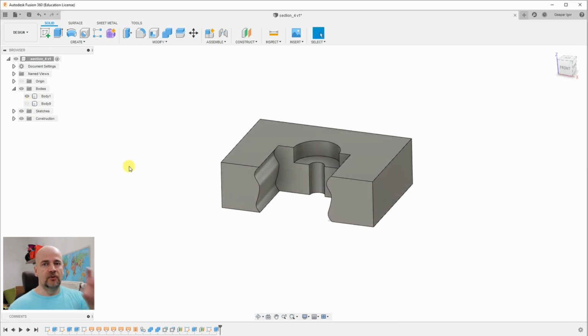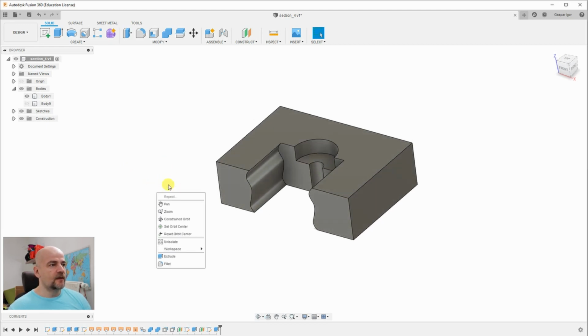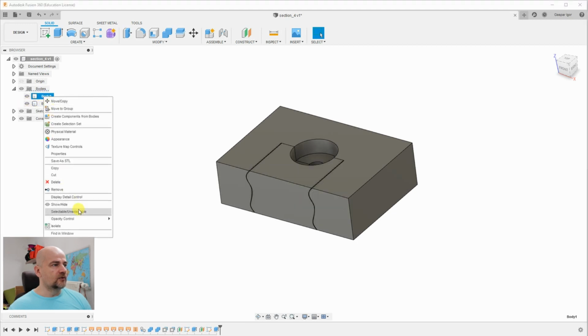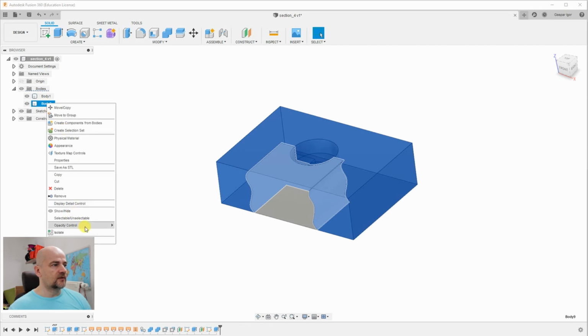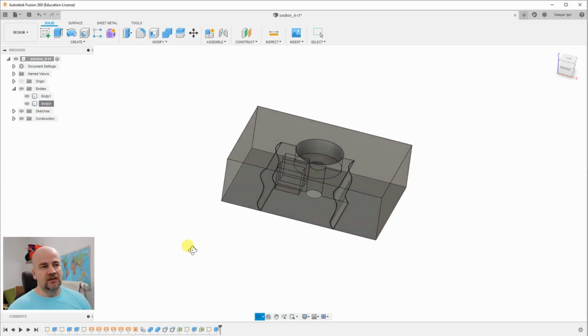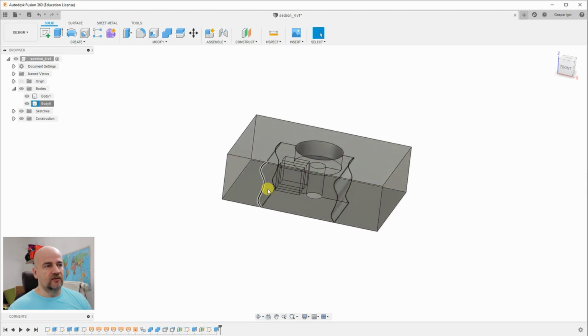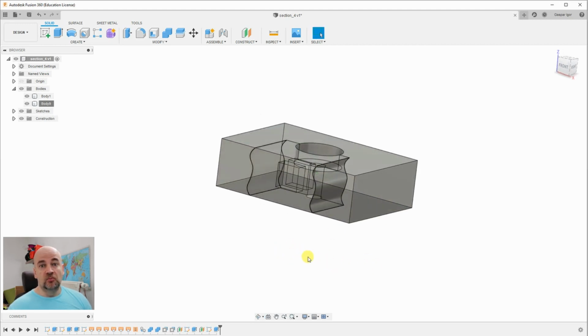So the students can pull out this object and see how it looks in reality. And of course I added holes here for the magnets. Let me turn on the transparency. So you can see here I will have only one magnet because it will be already very tight here. I added 0.1 mm of gap for 3D printing, and I don't have to use any supports.